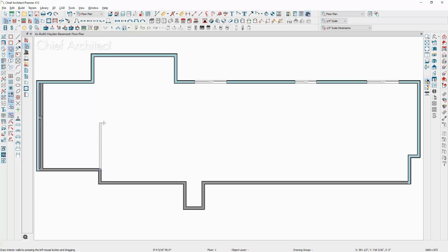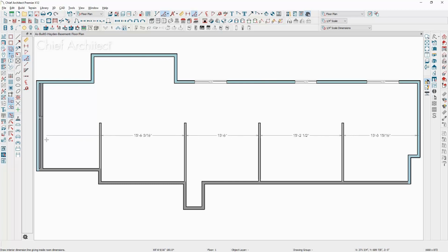The easiest way that I've found is to get them all in. Say I know there's going to be maybe 5 or 6 walls along this run, I'll put them all in, but I won't bring them all the way out. I'll just stub them out. Then when I start with the laser, I go from one to the other, to the other, and I end up with the whole line. Then I can just go right down the line and set the dimensions for everything at once.